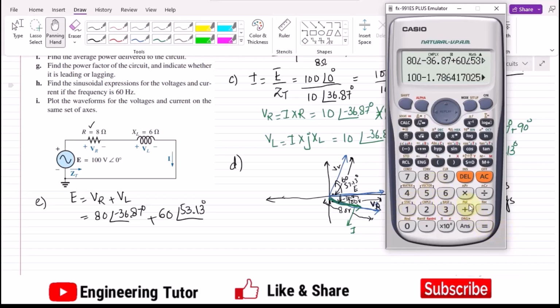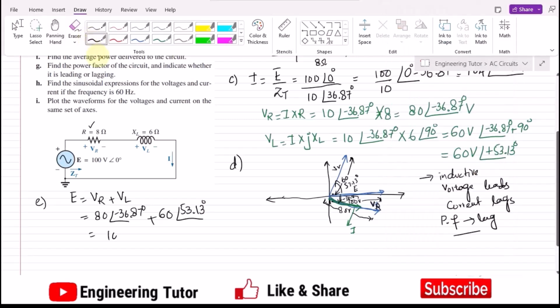Okay, so now adding them together, what will you get? You will get almost 100, and the angle with it is almost 0 degrees. That is the value of the voltage, which we may see is also here. So this implies that the KVL is validated, and Kirchhoff's voltage law has been proved. Okay, so this is the solution of part E.